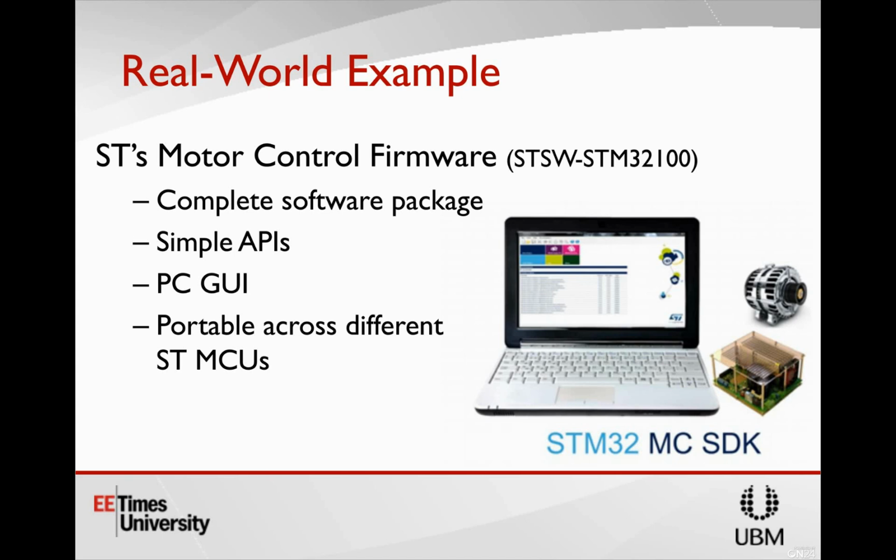And then there are other techniques. We didn't really talk about field weakening, which allows you to run greater than rated speed. There can be some advancements there, especially when it's combined with MTPA technology, which targets a very specific type of motor called interior permanent magnet motors. So I don't necessarily see the core algorithm becoming out of date. Where I see all the advancements is in the supporting features around it.